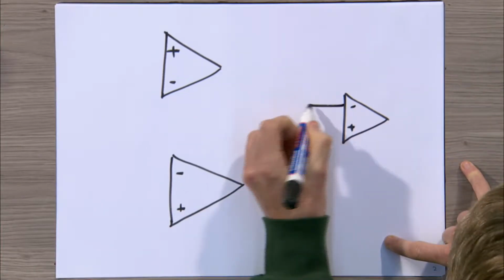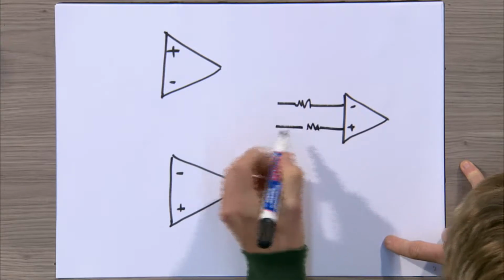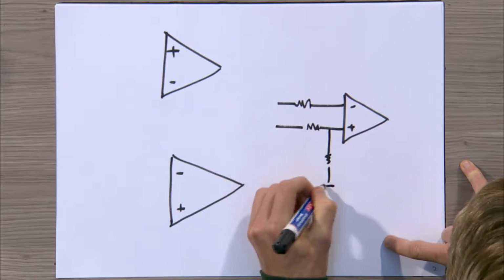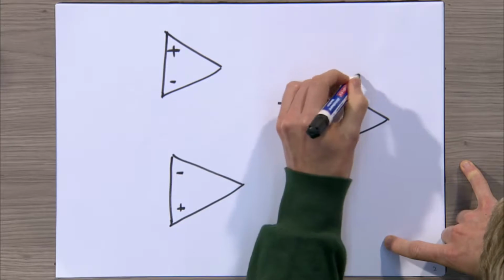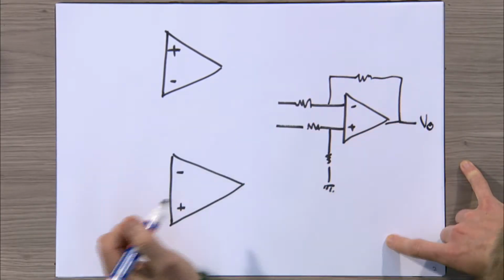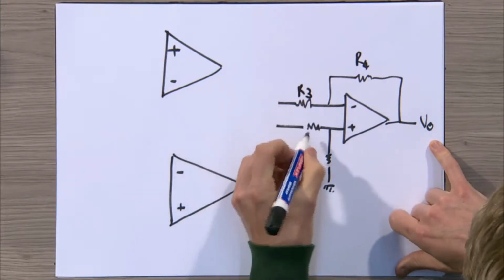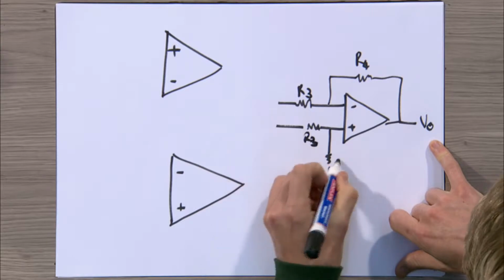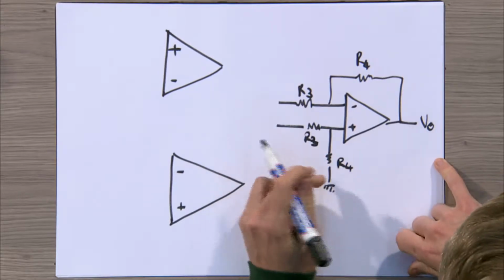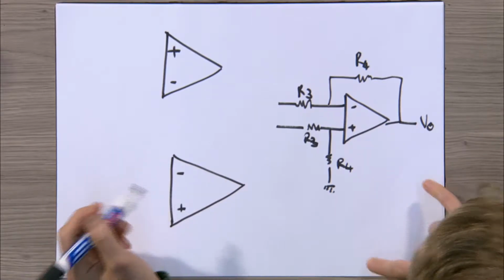Okay, so it uses a differential amplifier, like we've discussed in the last two lectures. So that should be fairly familiar to you. This output is the Vout, and these resistances we just pick to be exactly the same value, so we know that the ratio that needs to be equal, that requirement will be satisfied.